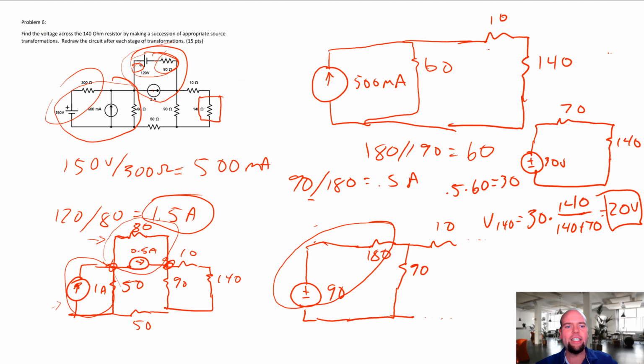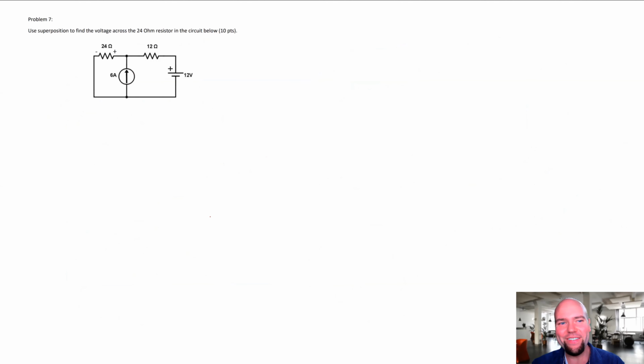You can always isolate the two terminals it's touching, right? This current supply and the resistor are here and here. Those should be the two nodes where your voltage supply in series with the resistor inserts. So a lot of times the mistake people make is when they replace it, they don't replace it in the right orientation, the right direction, and it messes stuff up. So try it on your own. Check your work versus my work. Let's hope my work was right from the beginning.